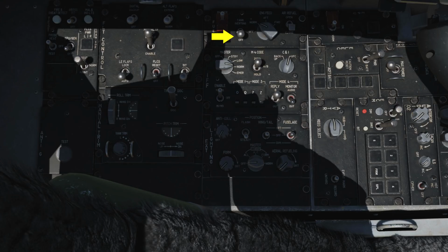Next to it is the tank inerting switch, which can pump non-volatile nitrogen gas into the fuel tanks to reduce internal pressure and reduce the risk of fire during an emergency, like battle damage. To the right of that is the engine feed knob that energizes or de-energizes the fuel pumps and maintains center of gravity fuel loading. The engine feed dial provides you automatic or manual aircraft fuel balancing.